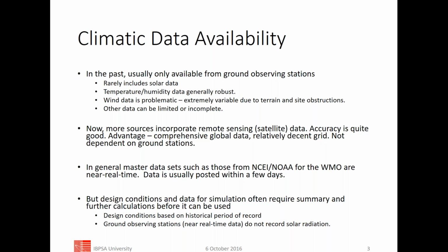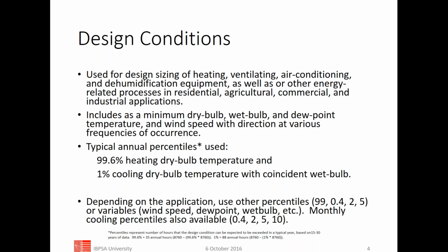But design conditions and other data sets, Chip mentioned deriving the TMYs from multiple years. The design conditions, we'd have to do that as well. So we have to do some calculations and statistics to be able to put up with that. So design is what we use to size heating and cooling equipment. It's basically peak conditions out there. Usually dry bulb, wet bulb, dew point, maybe wind speed is different conditions,